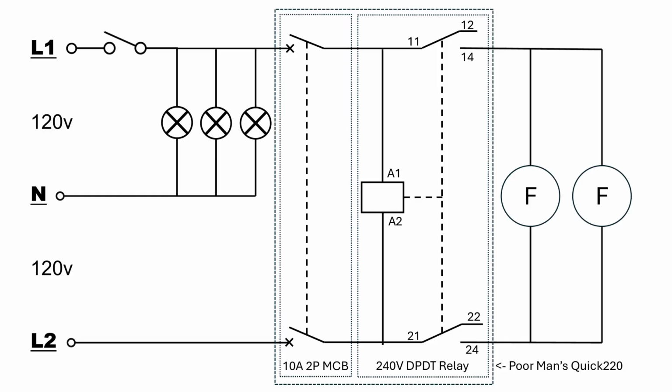And to clarify, a relay is more or less the same thing as a contactor, only smaller and rated for less power than a contactor. Alright, at this point, most of you should have probably figured out which component was causing the lights to flicker, but you are still probably figuring out why the circuit would behave like this. So I've gone ahead and simplified the block diagram into a schematic diagram that we can follow using IEC inspired symbols where possible, because screw NEMA!